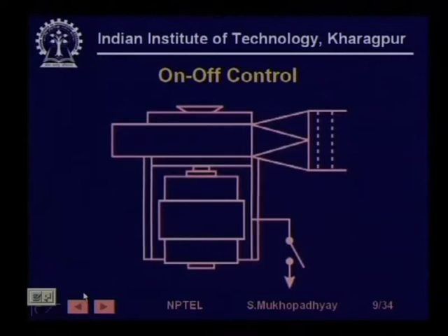Similarly, another major application for flow control is cooling. It is not good if sometimes you send coolant and sometimes you do not, because then the temperature on the equipment will be pulsating, and this may affect reaction rates and may cause thermal stress on the equipment. So, in general, for industrial flow control problems, we cannot tolerate such pulsations. Therefore, this on-off control method is not good. So, we go for other methods. What are the other methods?